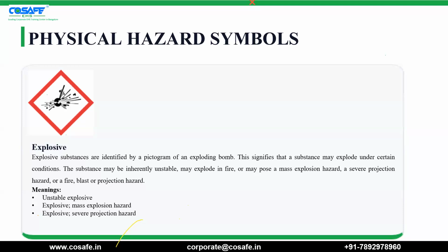Are you clear about the storage and criteria of petrol and all? Yes, sir. So see, just imagine in your factory you are storing 1,000 liters of petrol but in different containers, then you are not required to apply for this explosive license. If you are storing it in a single container, you require an explosive license. And if the storage of petrol in different containers exceeds 2,500 liters, then you require an explosive license. Got it?